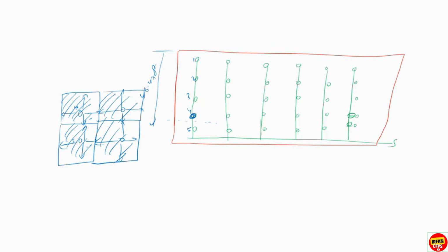Now, if the 46.47, the length of the design area, is coming below this line, below this coverage, I mean, if my line is here, it means we'll consider only 4 sprinklers, till the 4th sprinkler.